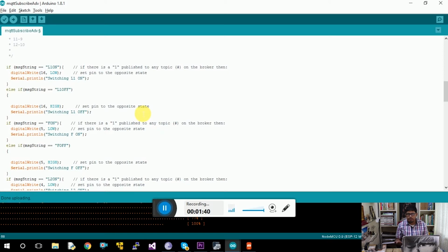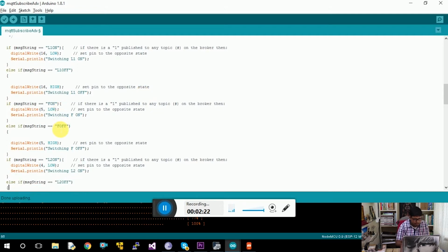We open our mobile, connect it to the hotspot, and then an HTML page pops up. We enter the credentials of the Wi-Fi, SSID and password, into the HTML form, click on the submit button, and those credentials get saved to the Node MCU's EEPROM memory, which can be retrieved at a later stage. Like if I'm using my home Wi-Fi right now and I switch off the Node MCU and switch it on again, I don't need to manually configure it again, because it just retrieves the credentials from memory and connects itself. So pretty much it's a very useful library, as far as I have found out.